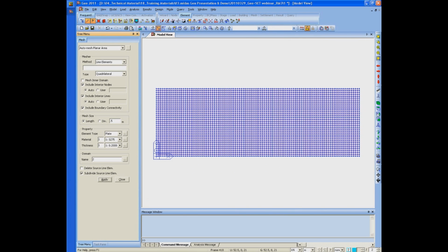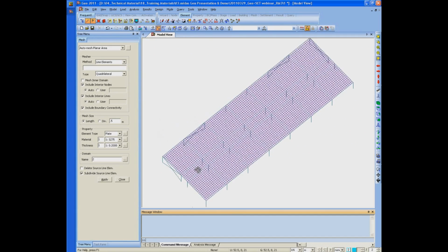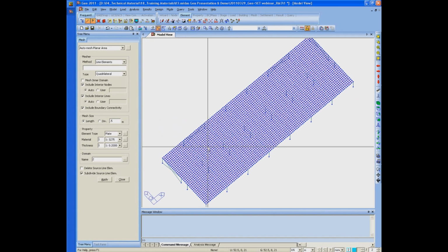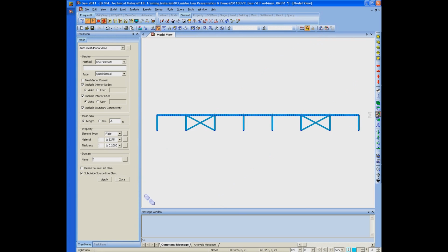As you can see, if you have any hollows, you can first generate the hollows, and then the program can consider that hollow so as not to generate meshes in a certain area. Or we can select certain elements to make the hollows based on the real requirements.